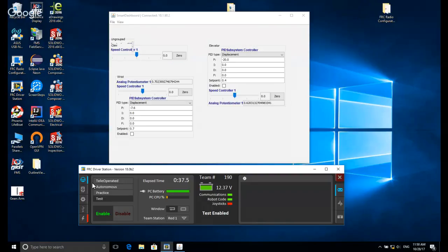If you're using an encoder, it doesn't work like that. With an encoder, when the robot turns on, you have to re-zero it in some fashion. Every time you turn it on, it's 0, and it doesn't matter what position this thing was in. It's saying 0 because it's counting how many of those little slots go by. There are some absolute encoders which effectively work like potentiometers, like expensive potentiometers. But you still have to go past the 0 position on them to re-zero yourself. So they're absolute, but if you reboot, you still have to go through the travel range in order to find the indexing pin on the encoder.